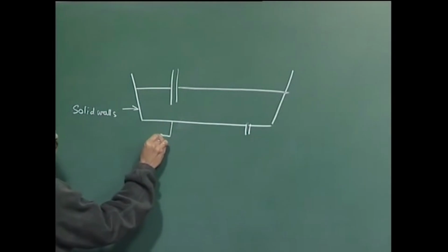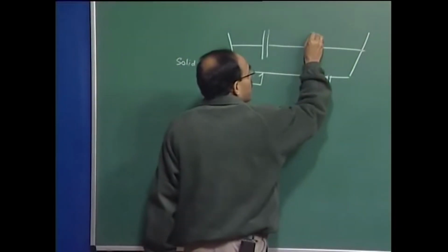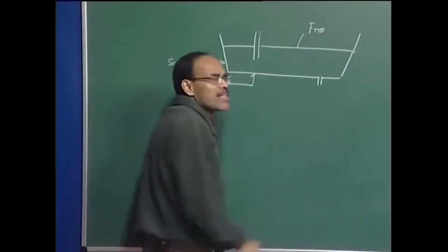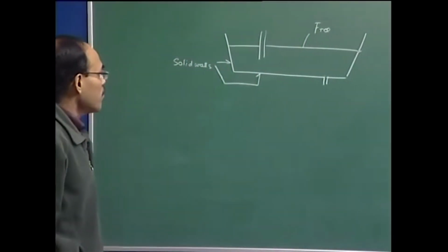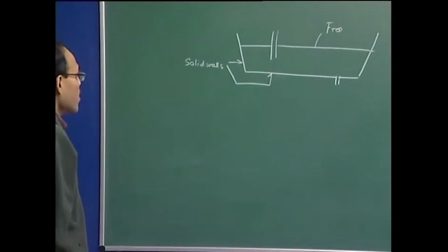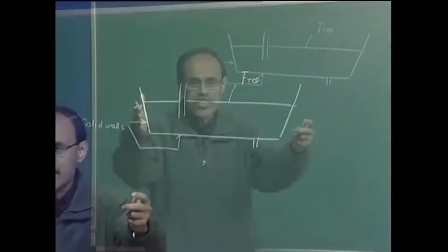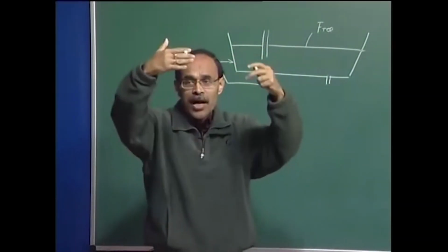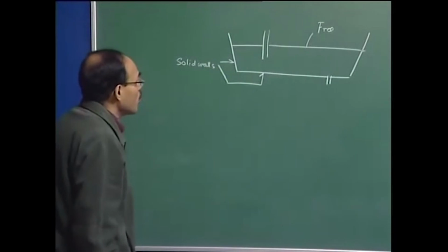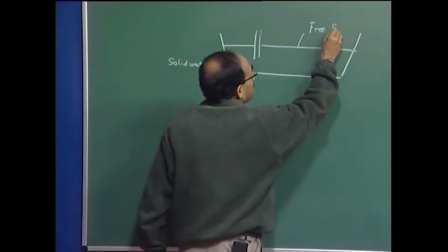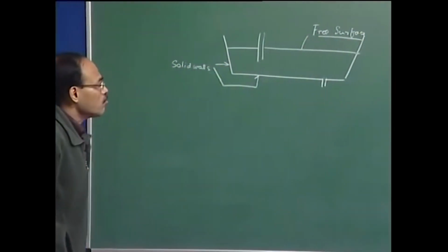This is also solid wall. We have a free surface. So, in most of the cases when you are talking of melt flow in BOF, ladle, tundish, mold, etc., 4 to 5 of our surfaces could be just the solid walls. For example, if you take the mold of continuous casting, you have copper cooled mold and we have 4 surfaces of the mold considered as the 4 physical walls or solid walls, and also we have a free surface. Free surface is a characteristic of steel making reactors.